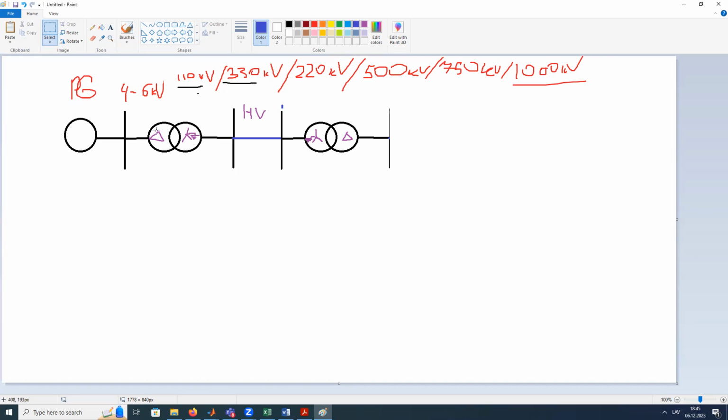So the time is limited, and there are two ways to deal with this: relay protection should detect and disconnect the line part that has a fault, or people should go and find it and disconnect manually. Two ways, because we have time, because this is not dangerous for the network, and this type of fault is quite difficult to detect because we don't have a high current. There are special solutions for this, for example the Peterson coil, or compensated neutral, and so on.